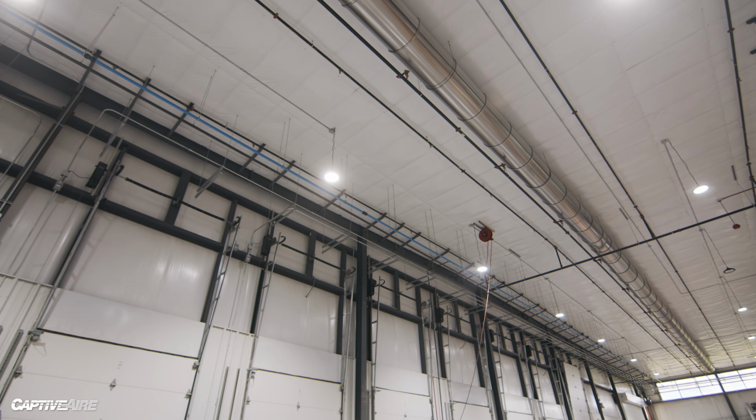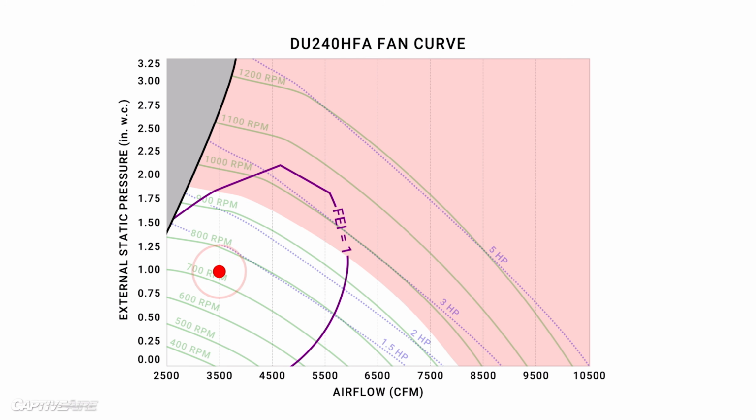So there's other benefits to it, but you don't necessarily want to be selecting anything down here because now you're bottoming out on that range and you can't slow the fan down if you oversized it. You don't want to be running up in this area because if you have any selections that you're right on that edge, maybe there's slightly smaller ducts or a 90 in the ductwork, some ductwork change that you didn't expect. Your static pressure might be slightly higher than you expected. So now you bump up and you basically don't have enough horsepower output from your fan.